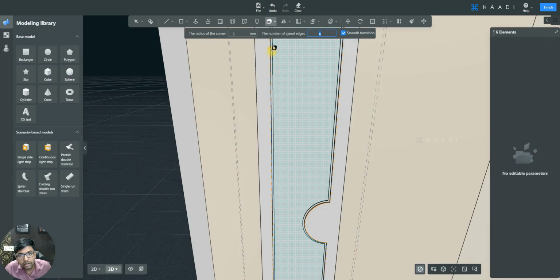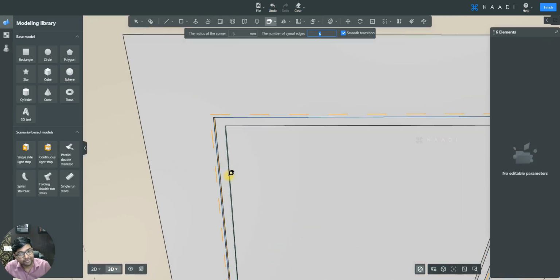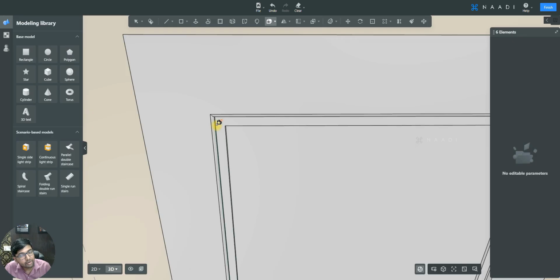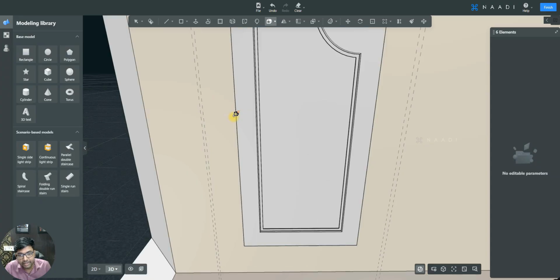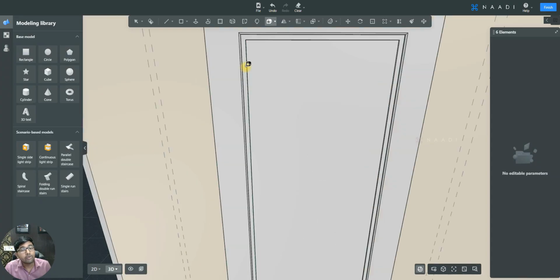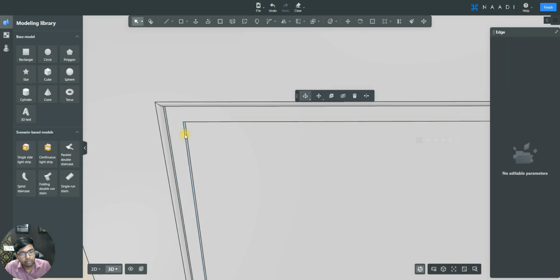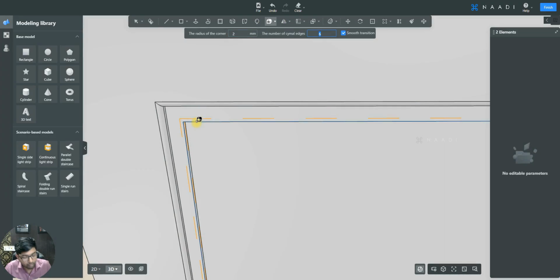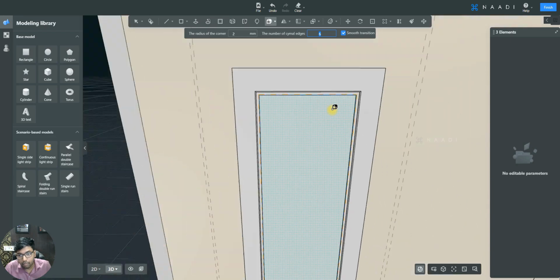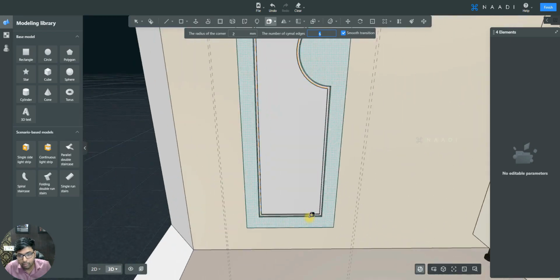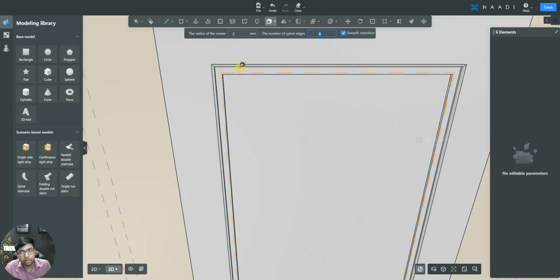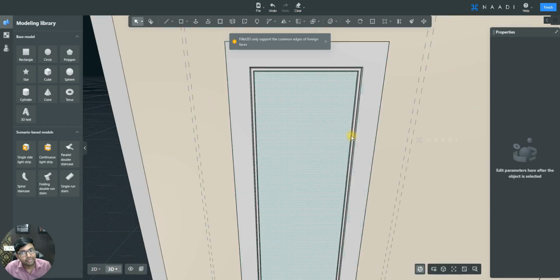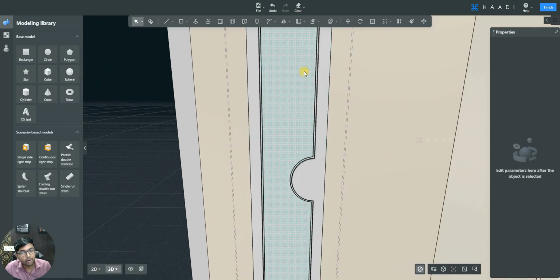And once that is done, just press enter. That's it. Your bevel for all the selected edges of 3 mm radii will be created. Can you see how precisely that bevel was created just in seconds? So now I could follow the same process to create a 2 mm bevel for the inner side. Now once all the edges for the bevel are selected, press enter. We precisely created a smooth bevel for all the edges here.